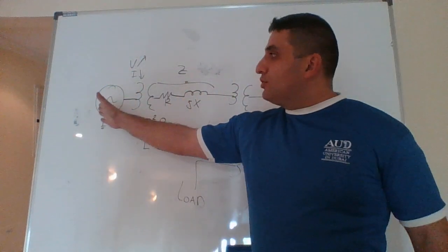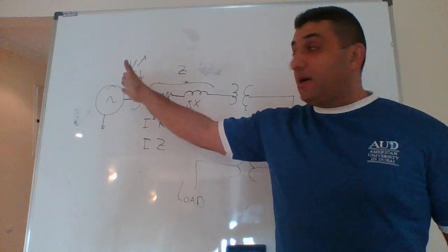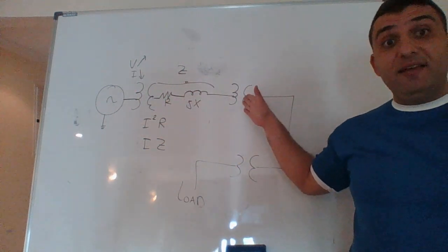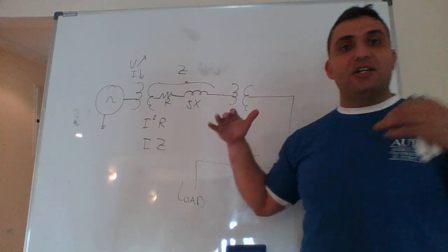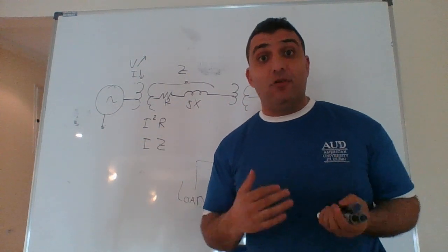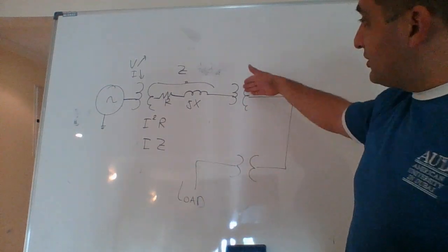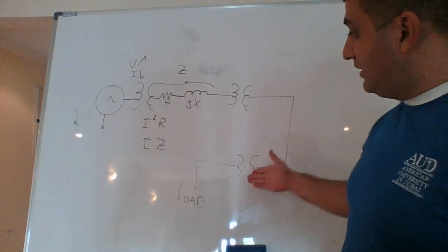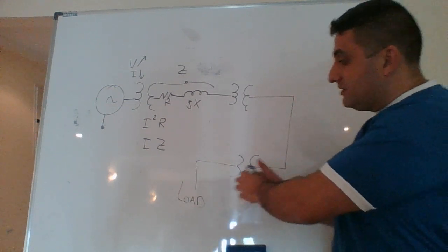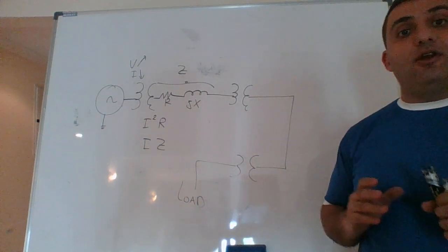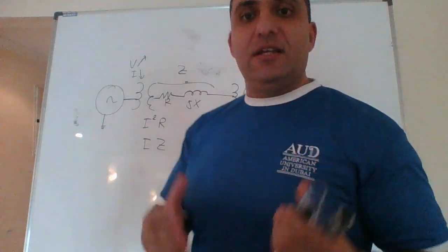So I could have a power station with a transformer to step up, and transmit the power to a transmission substation. There I have a large number of transformers and a large number of transmission lines, or as they are known, feeders, and then I go from the transmission substation to a distribution substation, or a zone substation in some countries, and all this will take me to the load. That's what I need to know now.